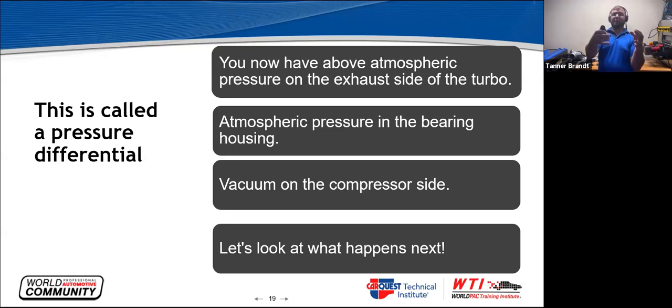So if you have a back pressure sensor like on the Ford Transits, and that sensor's between the turbo and the manifold, that's why you'll see high pressure there, because it's always going to mimic the boost pressure side, because it has to be the same pressure on either side of the turbo since there's no seal to hold the oil on the inside of it.